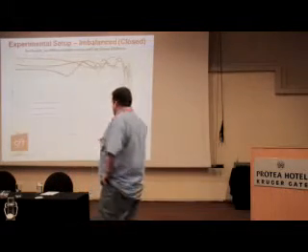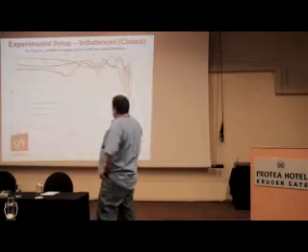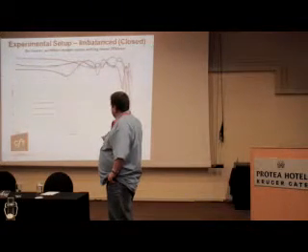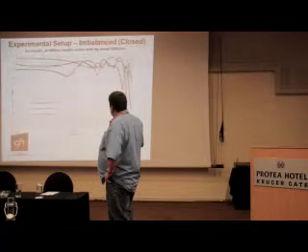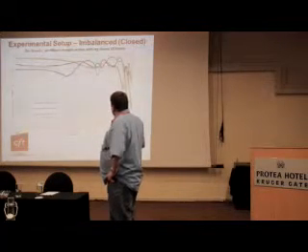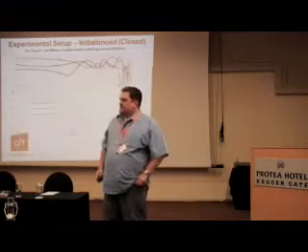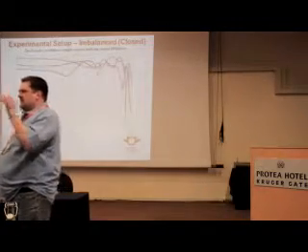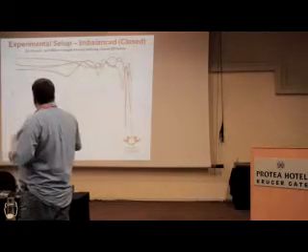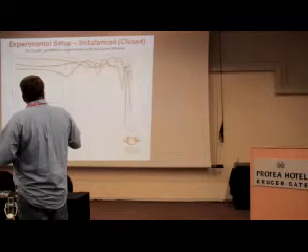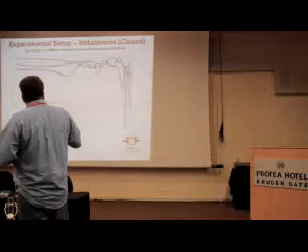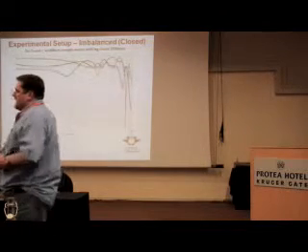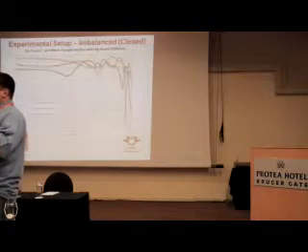What happens here is that in the beginning, yes, we've got the lumped circuit behavior, and then suddenly at a couple of megahertz, we start seeing transmission line behavior. Now the differential mode, which is the normal mode that you would usually tap off for the signal, is this green one. You'll see there's a little null in the green one, and then there's a big null at the end over here. And that is where MIMO actually works.